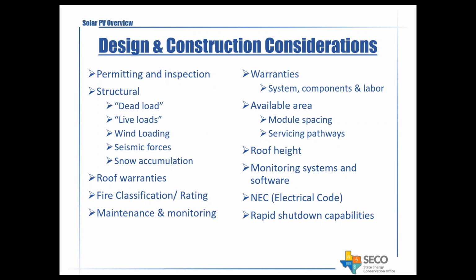The rapid shutdown capabilities are required by NFPA, basically. You need to be able to shut down these facilities in case of fire and so forth. This has been developed as these installations have become more popular, and these codes will still be updated as more progress is made and as more of these systems are installed.